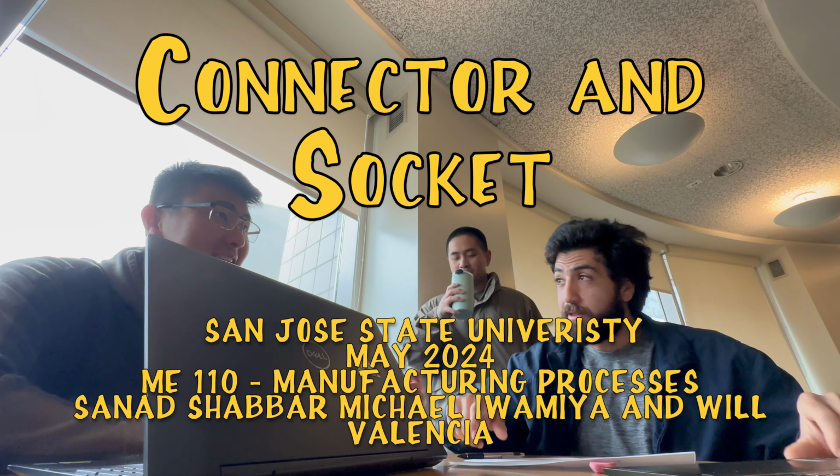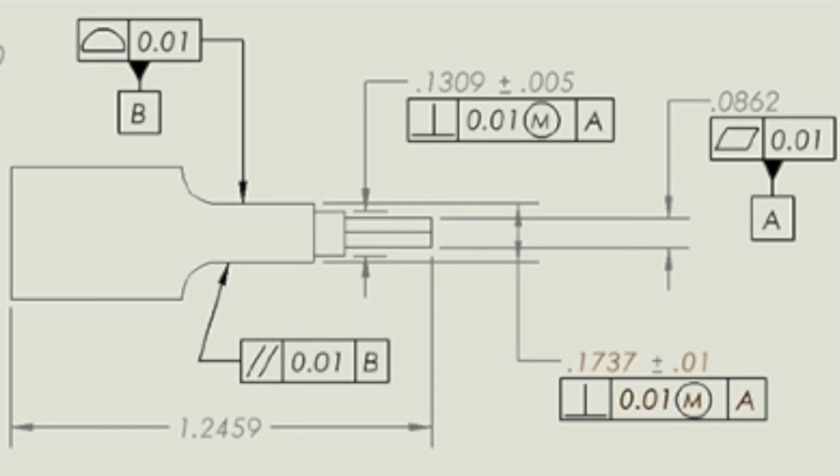This is our drawing for the male socket of our assembly. Starting in the upper right with a side view of the part, we establish our first datum A to take away 2 degrees of freedom on the very back side of the part with a flatness relation and tolerance zone of 0.01 inches. Furthermore, the part is stepped twice to larger thicknesses of 0.1309 and 0.1737 inches, respectively.